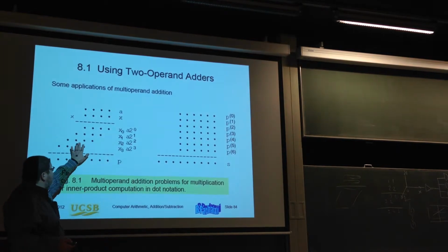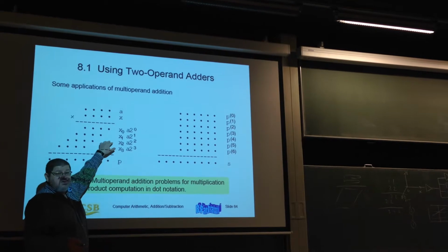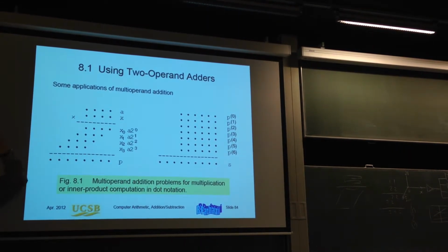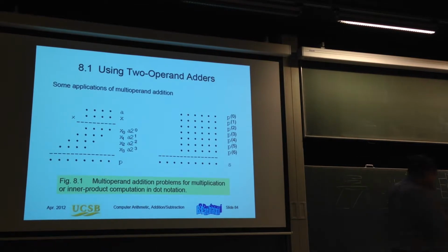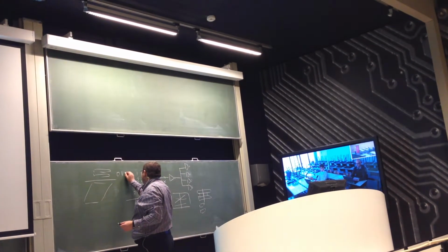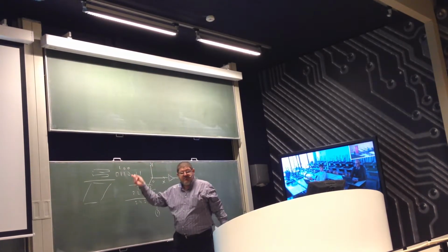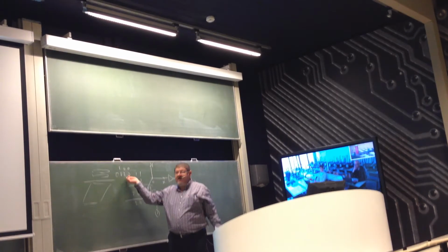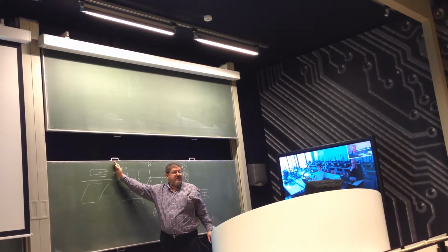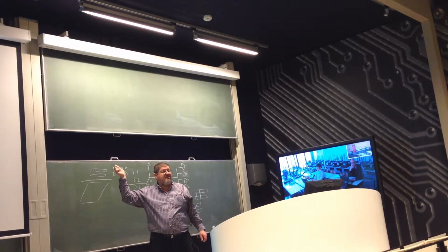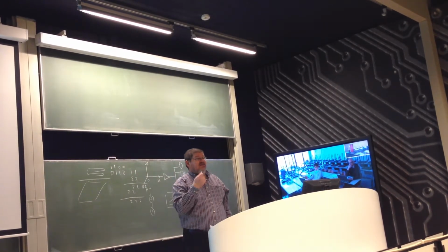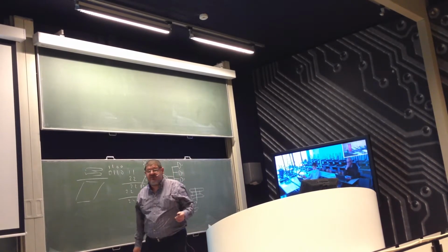The fact that this is not rectangular doesn't matter. In here I have zeros, and in here I have to do something to deal with the sign. We most of the time do sign extension. Remember when I was discussing those complement numbers, and we said that you have to sign extend because otherwise the value will not be preserved? Then if I add 0, 1, 1, 0 with 1, 0, 0, those are in two's complement. This is a positive number, and this, if I look at it only at 3 bits, is a negative number. If I want to preserve the value, I have to repeat the most significant bit. This is called sign extension. You look at me like you never heard about that. And I'm pretty sure you heard because I discussed it. Then basically on that part of the matrix, I can do sign extension.